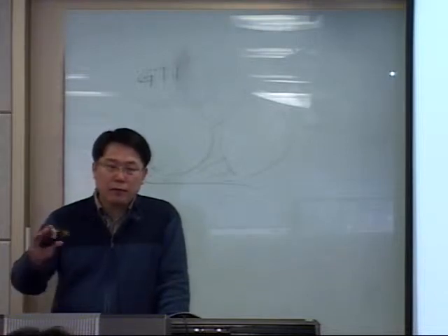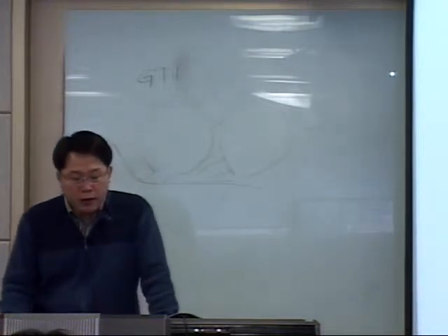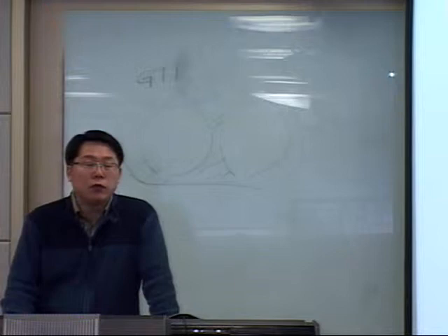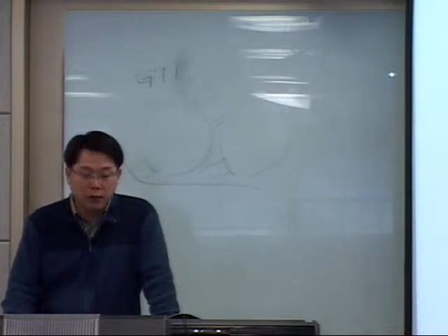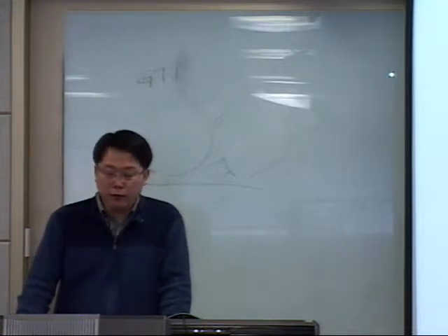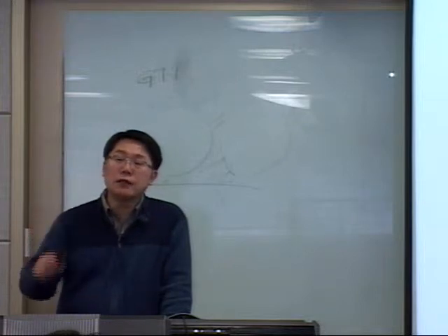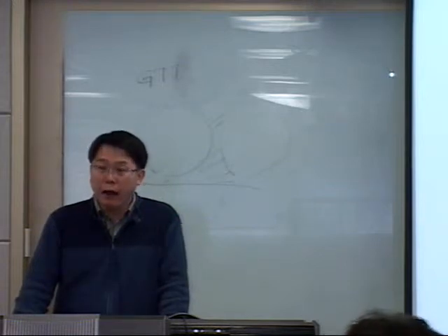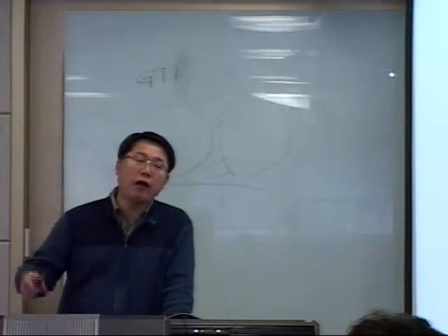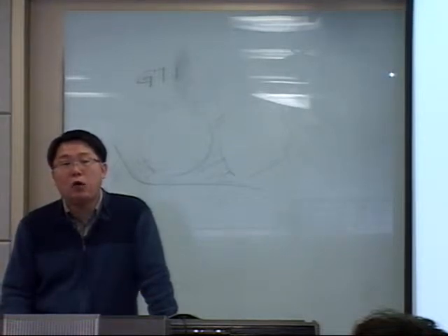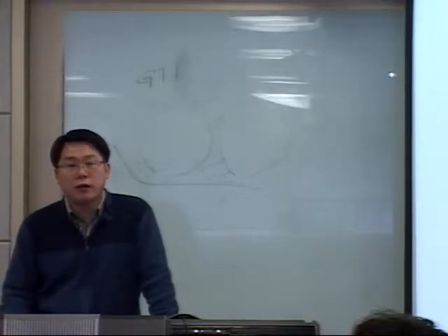There are several protection layers. First is if the pressure is too low, less than 1 bar, we call that kind of state vacuum. If the cargo tank is under vacuum, we need to insert some gas. Maybe the easiest way is to insert the air, but if you insert the air, the ambient air within the cargo tank would be flammable.